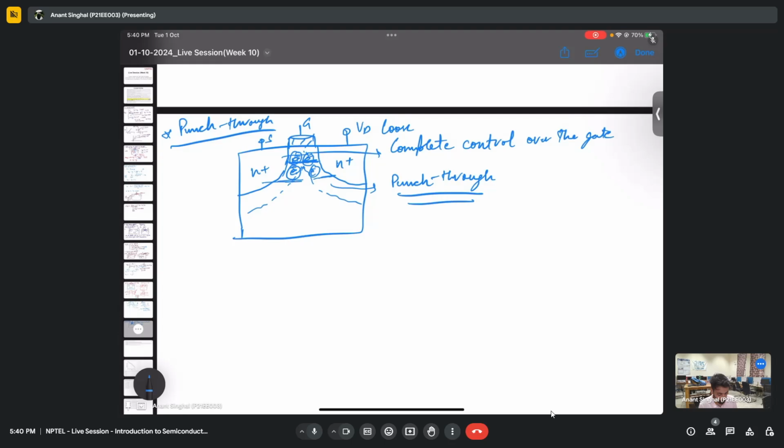It will not stop electrons from going from here to here. It will never stop because it is a depletion region. As soon as we have an availability of electrons, they will go from here to here readily. There will be a continuous movement. Yes, there will be a repulsion because of this Na minus, but they have to go from somewhere to somewhere. But the depletion region doesn't allow any free carriers to stay there, right? Yeah, it is not staying, it is going from here to here.